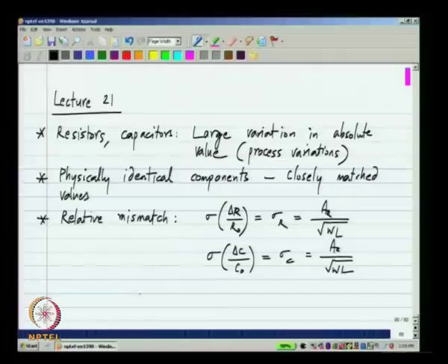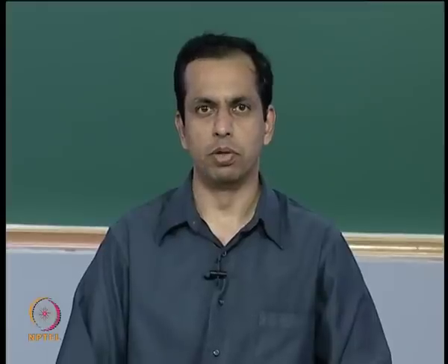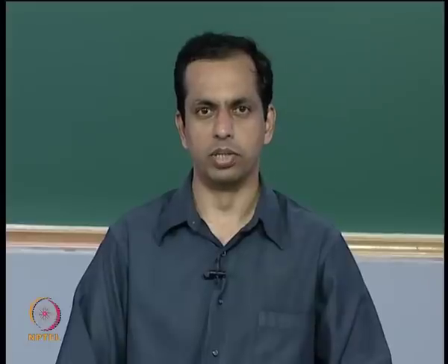We will see later that this is true not only of resistors and capacitors, but also of all other components. They all have a similar behavior with mismatch. If you want closely matched components, you need to have physically large components.